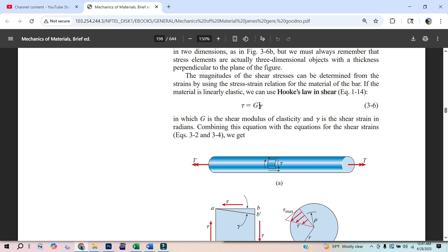So you have a really small number, 0.004 times 11 million is 44,000 pounds per square inch. Angle of 0.004 radians. So this number has to be 11 million pounds per square inch divided by radians. And because radians is dimensionless, this is just 11 million pounds per square inch. Hell yeah. All right, I was pretty satisfied with this one.